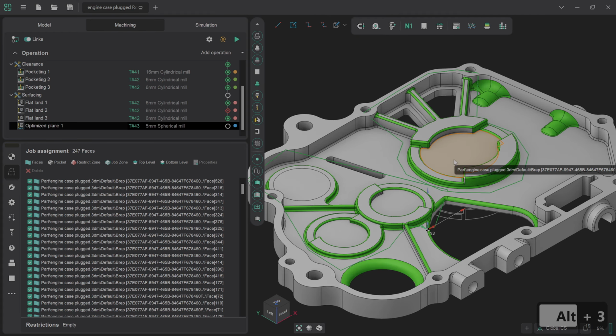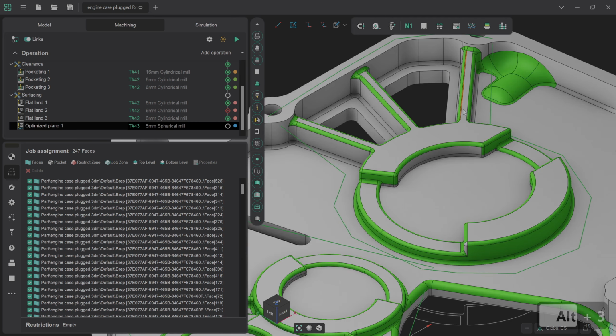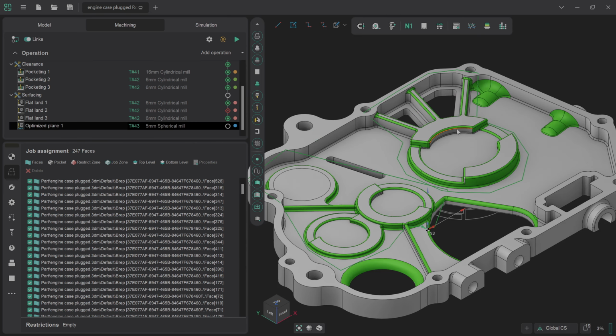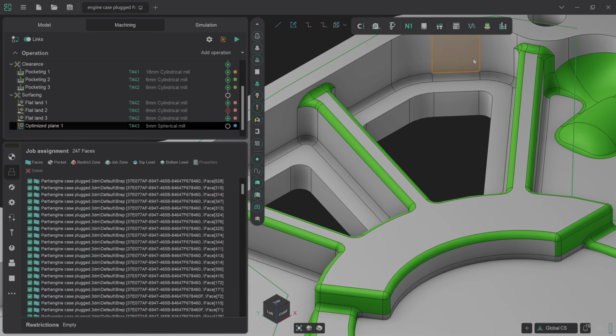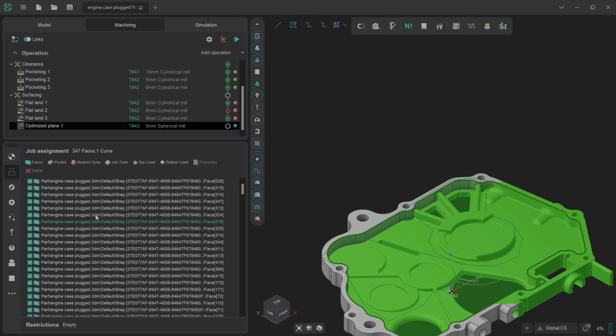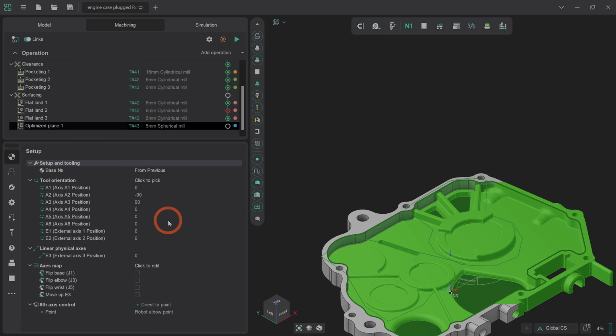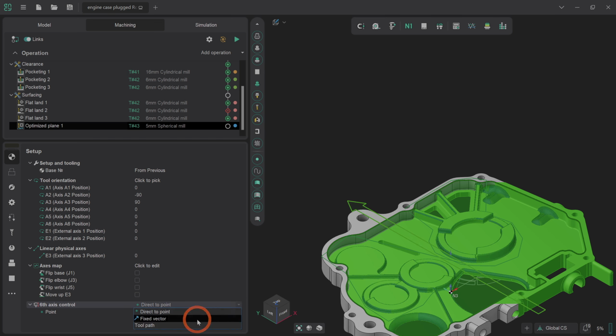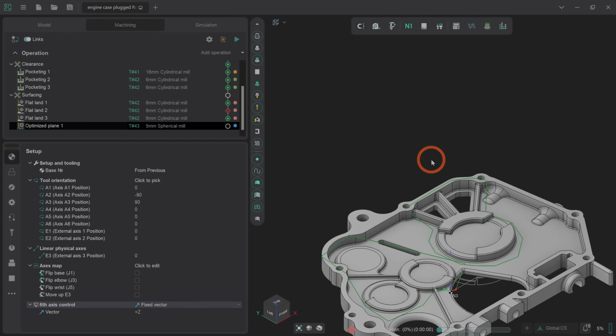Okay, so we're now back and we have selected all of the most important curved faces here. I've not necessarily bothered with ones that can be covered by a subsequent profiling job, but wherever there's any transitional faces like this, I have grabbed them. So now that we've defined these, we are going to define the job zone just so it doesn't go anywhere completely mad outside. And we are going to set the 6th axis control and then generate the toolpath and see what it comes up with.